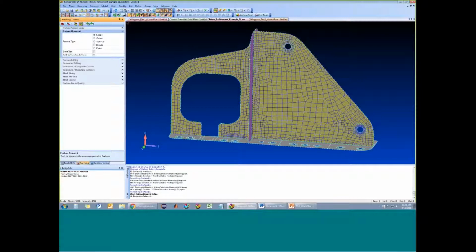So let's say we want to remove this split edge here. I would select curves. And then under curve options, we have our basic and aggressive as before, but now we also have combined surfaces. So I can select that, I can select that curve, and now it's gone. And this surface is a parasolid surface. It's actually there. It's not a boundary surface referencing the old one.